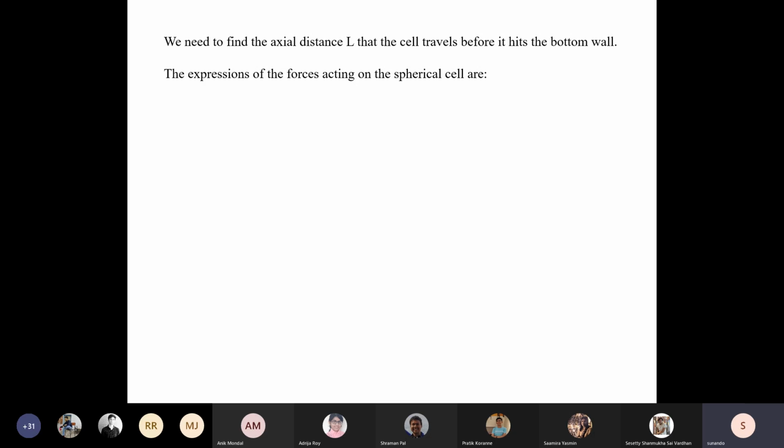So I would rather separate the drag force from the viscous force, but you are correct in identifying that viscosity is the prime cause for the drag force. So there are three forces which are acting. One is the gravity force, the other is the buoyancy force, and the third is the drag force. Is there any relation between the three? The gravity, the buoyancy, and the drag?